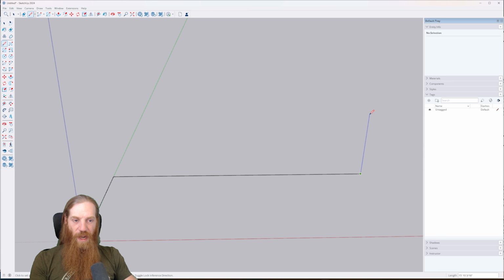So you can see it just snap to the blue axis there. I can move the cursor a little bit around that and it's going to stay right on that axis. Same thing with the red axis, green axis. So that's important because right here, from my perspective, it looks like this is coming straight towards me to make a nice 90-degree angle for that corner of the building and then bring that wall towards us, right? But notice it's on the blue axis. Which axis is the blue axis? It's the vertical axis, our z-axis, if you want to call it that, right? It's our up and down.